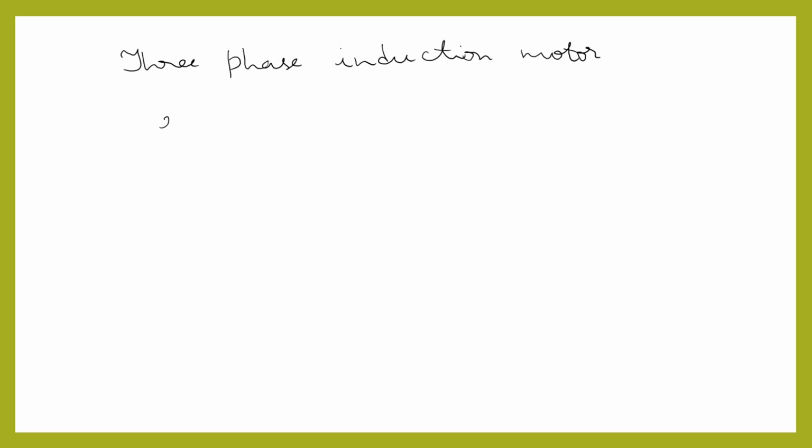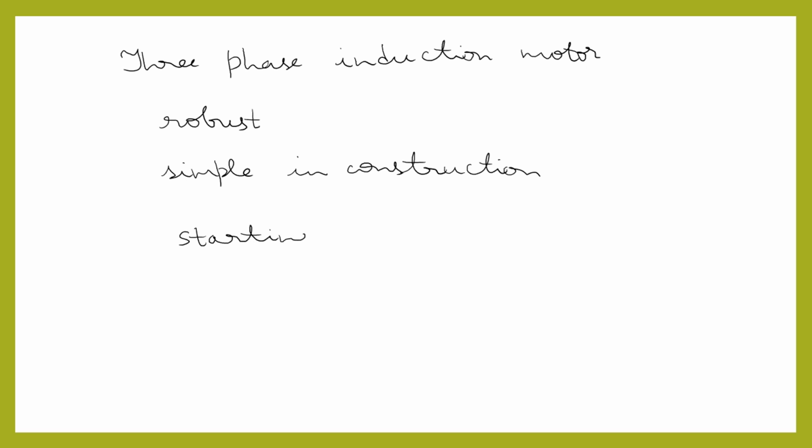Though the construction of the three-phase induction motor is simple and robust, there are a few drawbacks of the three-phase induction motor. That is, there is difficulty in starting the motor, as well as speed control of the motor, which doesn't make it suitable for traction work.